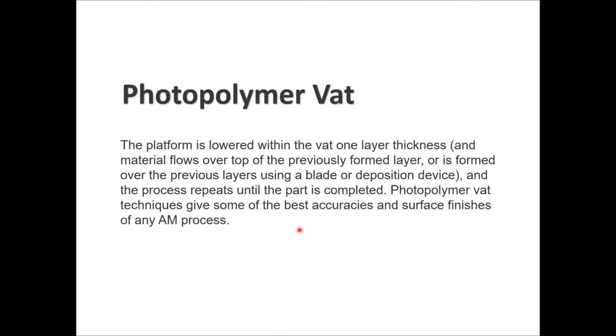So the platform lowers within the vat one layer thickness. The material will flow over the top of the previously formed layer. So it forms the new layer over the previous layer using a blade or deposition device. And the process will keep repeating itself until it completes the final product needed.